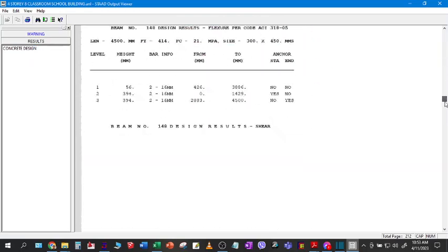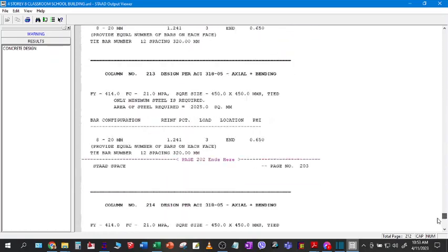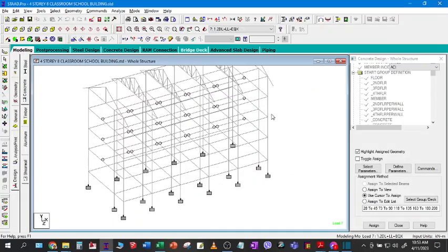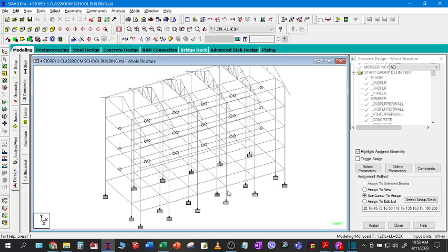Okay, so this is a very lengthy report, but if you are already well versed in STAAD, you will look at the analysis and then look for the members with similar results for shear and moment, and then you can only design the part which you want to design and maybe copy that design to all the other similar members.